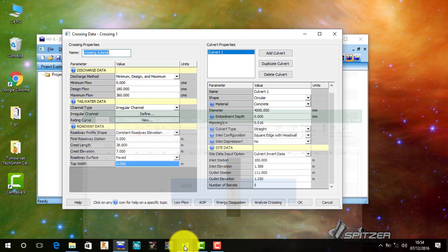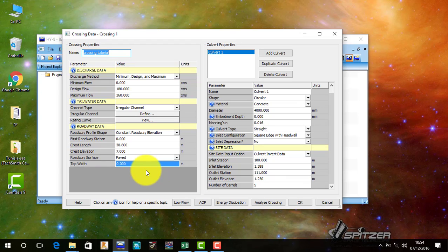I would choose 3 meters for each lane and 2 meters of security. Then if we have a road of 2 lanes, we have 3 multiplied by 2, which is 6, plus 2, 8 meters. Our road's width is 8 meters.